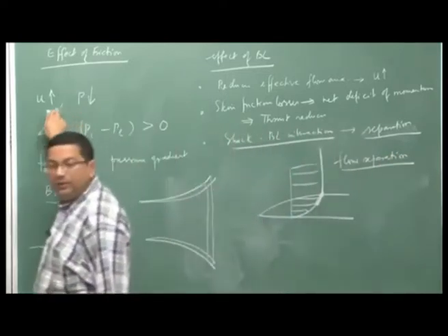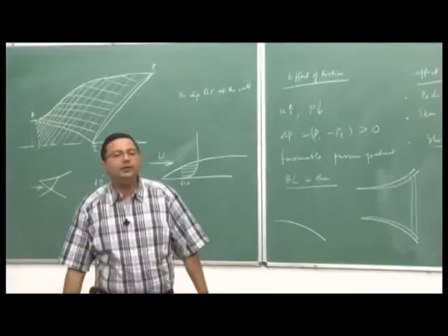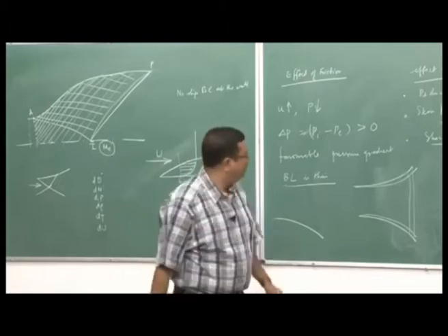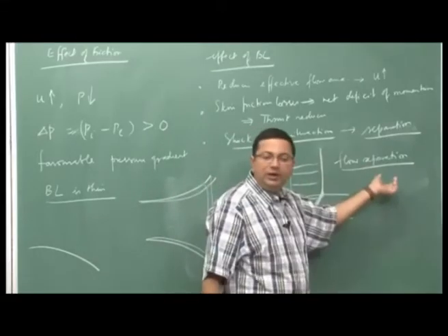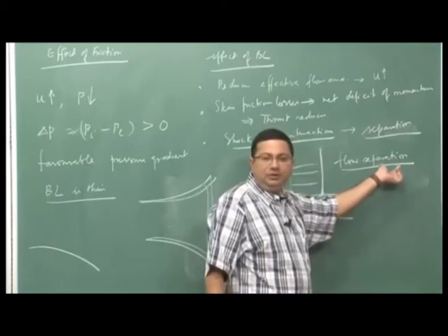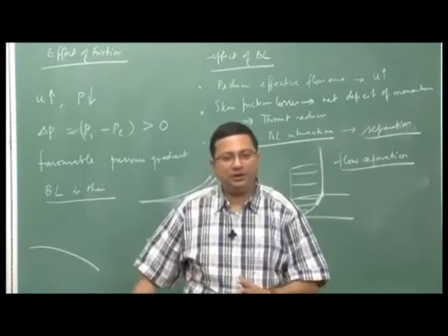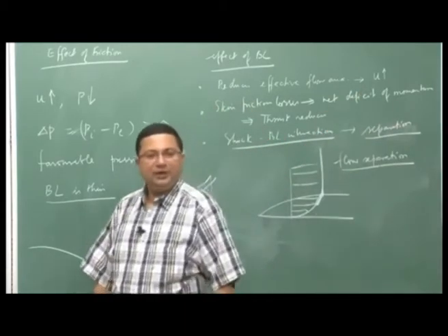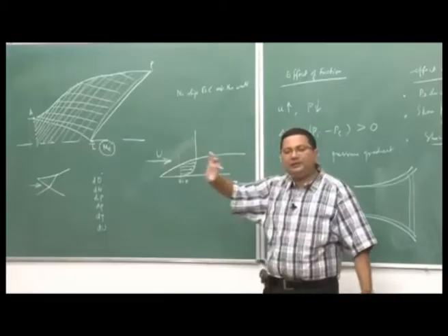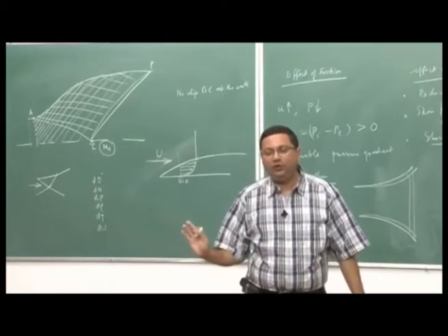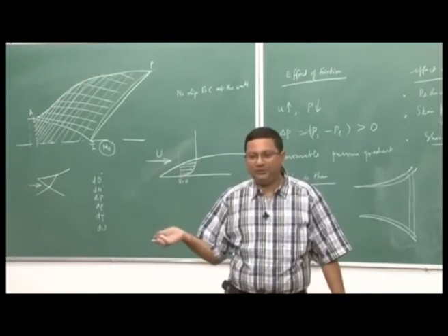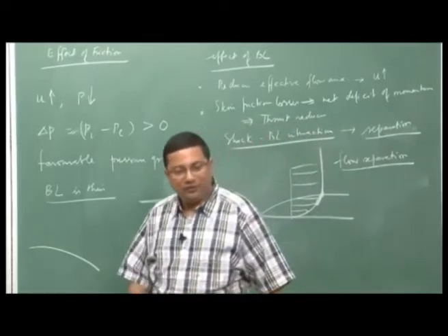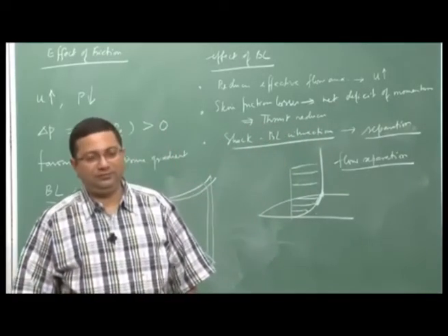So, even though we have a favorable pressure gradient in the free stream, in the boundary layer we may not have a favorable pressure gradient, and that may lead to flow separation. The shock waves can interact with the boundary layer, which will enhance this flow separation, because the shock wave will make the boundary layer further subsonic, right. So, all these lead to a possibility of flow separation. Even though the free stream is accelerating, there is a very nice clean flow, the boundary layer can bring in a lot of problems. So, these are something that needs to be addressed when we are designing a rocket nozzle.